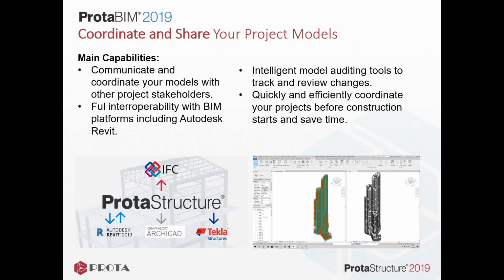And the idea is that you can send models out to, say, Revit, where we have bespoke links, and you can start the process of coordination on your project. So you may be sharing it with an architect or other project team members. You can take the model into Revit. You can sit down and coordinate things within Revit. If there's changes, models can be updated and then communicated directly back into ProtaStructure. And you can do this as many times as you like to coordinate your projects.